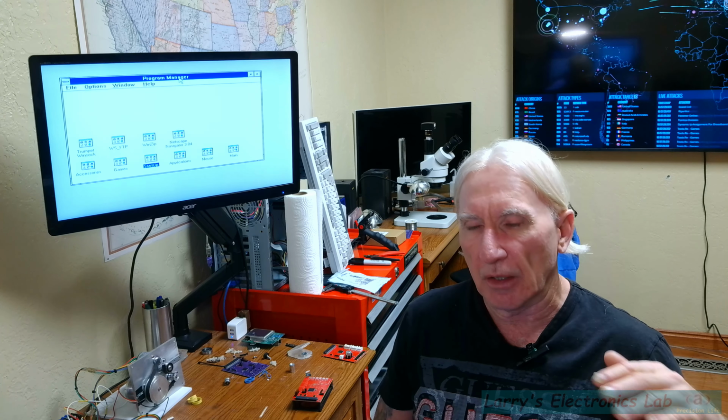It has clock switchover, so you can power it up on the internal. There are 2 internal clocks you can use to power it up. And once it's powered up and running, the idea behind that is it saves power consumption. Then once you get rolling in your firmware, you can switch over to a faster or a different clock. MainBrain uses an external oscillator for the primary oscillator.